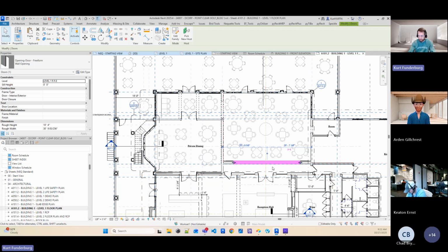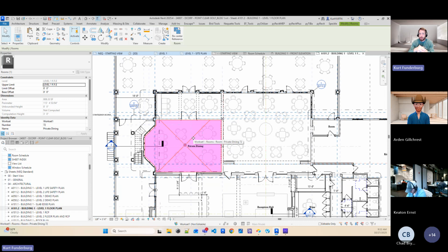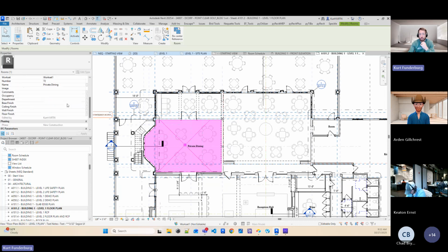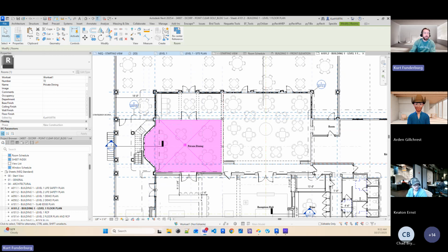So in a sense, this patio would merge with this space out here, and it would be viewed as one big space. But within the room is where I was talking to Audrey and Rebecca about when we create a room finish schedule. We can add project parameters to rooms, and we can talk about this with shared parameters that we can add to each project so that they're the same parameter that we look at. That way, when we combine multiple buildings into one, it's all in one place: this is the ceiling finish for all these rooms, this is the floor finish.